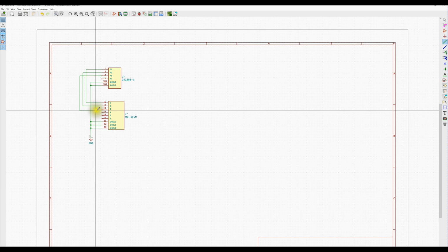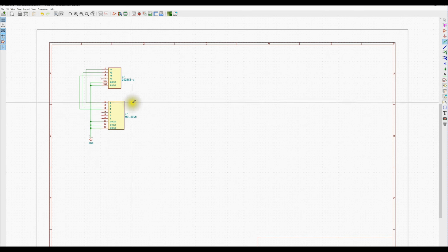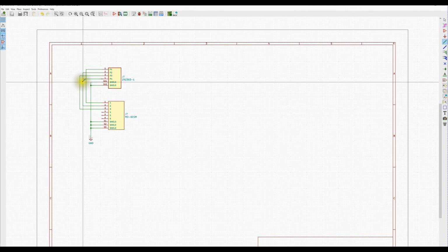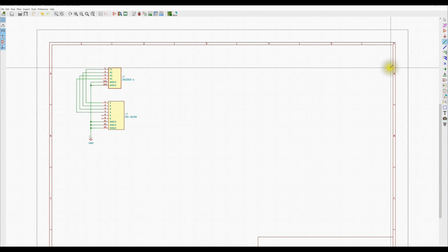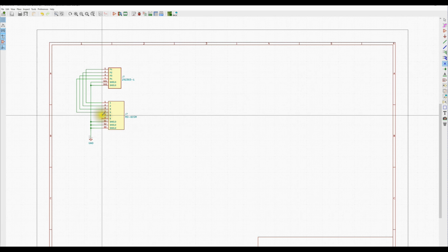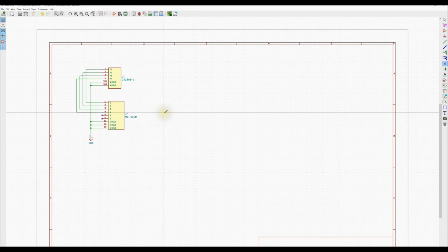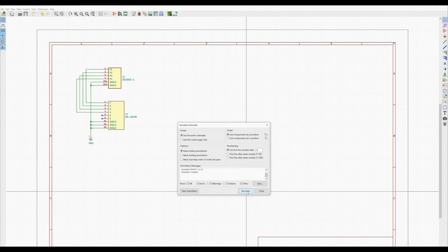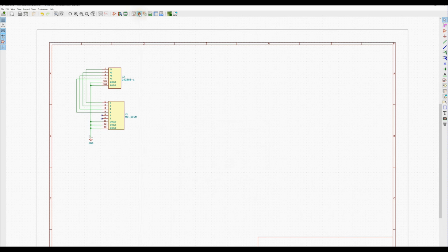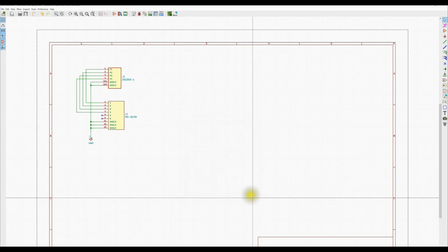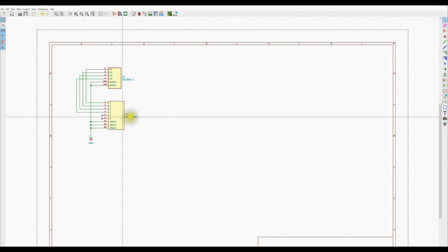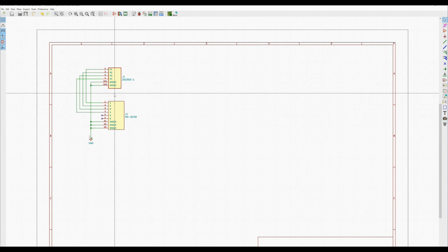Now I have gone in myself and actually modified footprints to put the pins on the side I want to make the schematic a little simpler to draw. I'm going to call 5 and 6 no connects. Let's go ahead and label everybody. I suspect we'll get a not driven. I'm going to ignore it. I'm going to save the schematic, drawn as is, even though maybe you do an adapter board for this, but this is ridiculous.